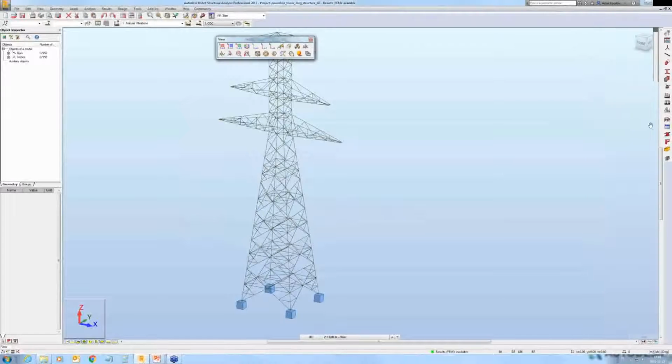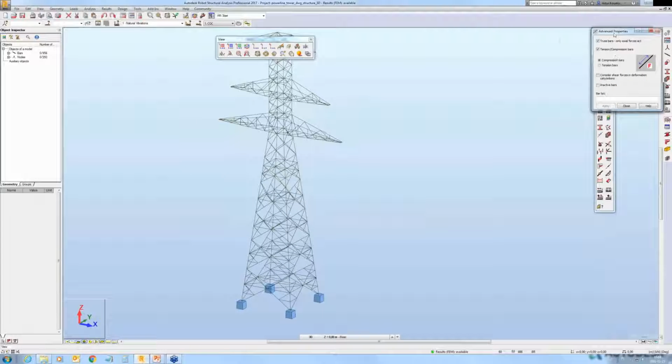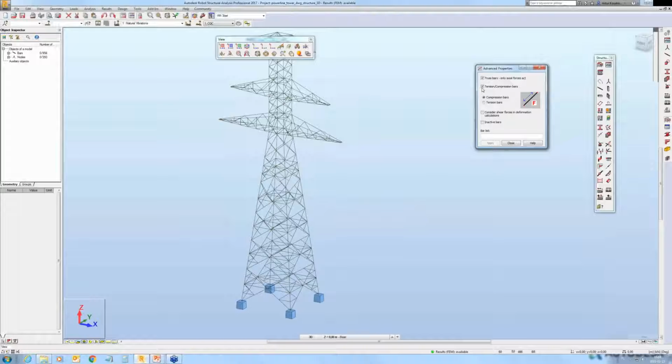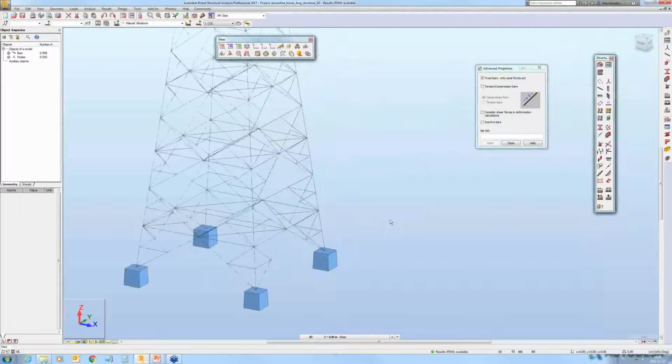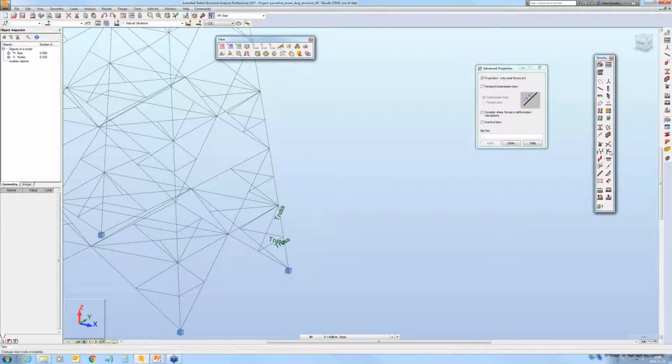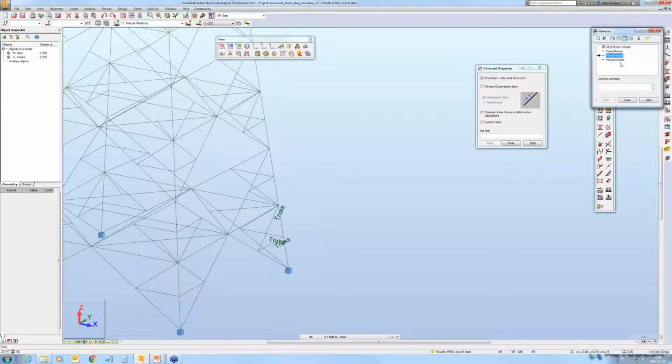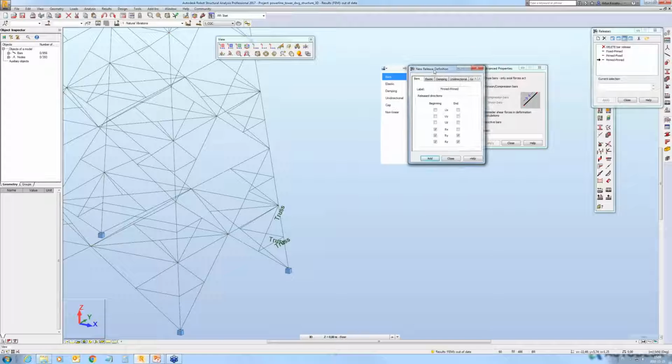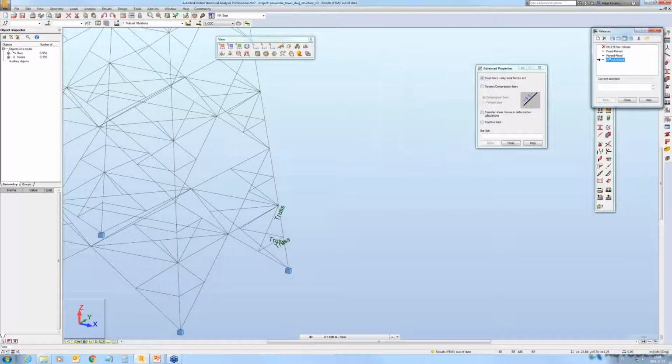So in this situation, I need to define truss bars, the elements that cannot transfer bending, and you can define truss bars for these short elements here, but for the elements that are built from a chain of elements, you cannot use truss elements. That will result in instability, so you should define releases instead. In this case we go for fixed-pinned.